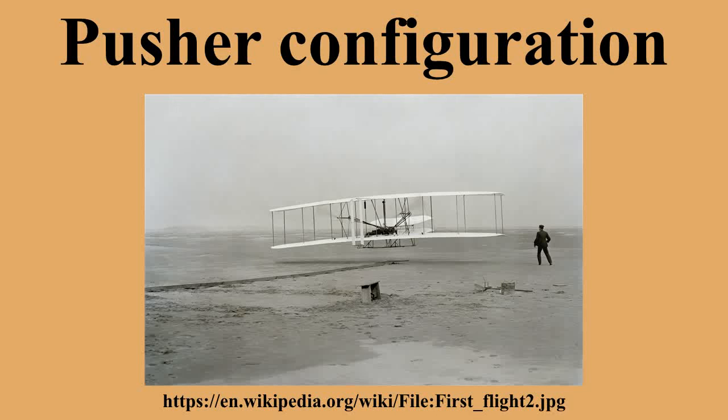The engine may be buried in a forward remote location, driving the propeller by drive shaft or belt. The propeller may be located ahead of the tail, behind the wing or inside the airframe. The propeller may be located inside the tail, either cruciform or ducted fan. The propeller may be located at the rear, behind a conventional tail, a T-tail, an inverted V-tail, a Y-tail or a cruciform tail. The propeller may be located above the fuselage, such as a glider with a retractable propeller.